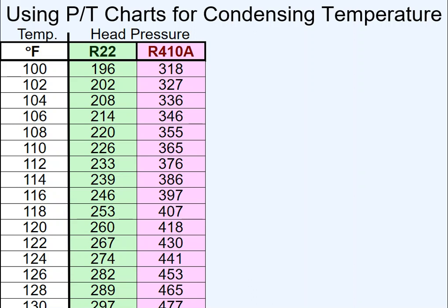But if you understand the theory of it, that it's more about temperature than it is about pressure, that all you're really worried about is the temperature inside that particular component in the system, then all the chart tells you is the corresponding pressure. A lot of people start out backwards, I think, and I started that way. You worry about the pressure and say, well, what should my pressure be? When you understand the theory of what's actually going on, I don't really care what the pressure is. Pressure is just a byproduct of temperature, because temperature is really what tells me what it's doing.